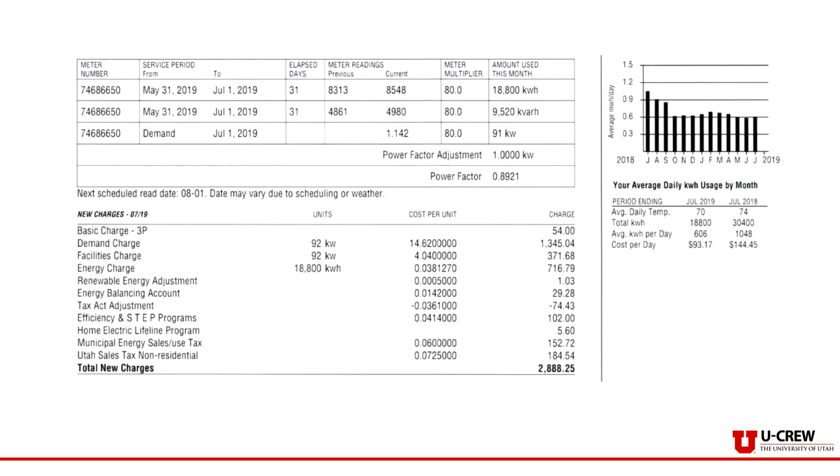As you might be able to tell, you're now looking at an electrical bill. The top might look a little bit confusing, but you can see that this is just for 1 meter. The first thing I want to highlight is the power factor. This facility has a power factor of 0.89, and if you remember, 1 is ideal, but this is pretty good. In fact, for power factors above 0.9, they don't even include it on the bill and don't penalize you for it. So this facility is almost where they should be.